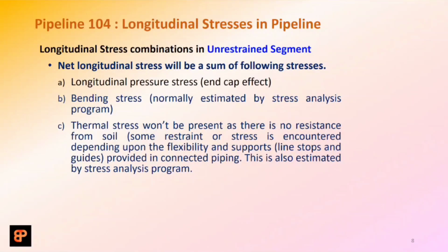Thermal stress, definitely the thermal displacement or thermal expansion or contraction is going to happen in this section of the pipe, but there will be limited resistance offered by only the associated bypass piping configuration and the supports provided, but not like the way buried soil is going to act and restrict the movement.